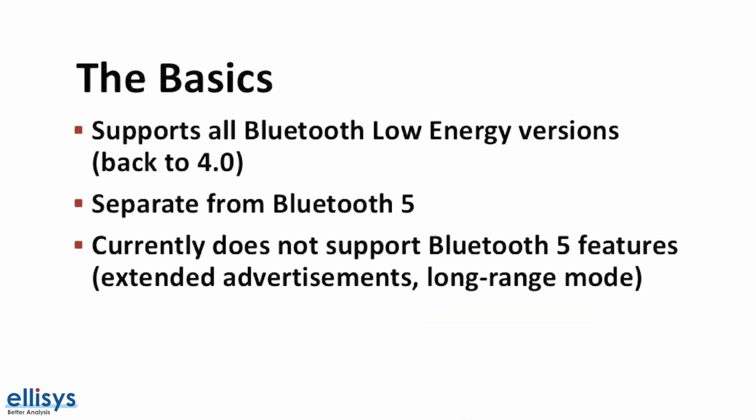A few important notes regarding Bluetooth Mesh. First, it supports all versions of Bluetooth Low Energy, going back to Bluetooth version 4.0. However, it is a separate specification and standard that's not part of the official Bluetooth specification. This is including Bluetooth 5 as well, and currently, as of the recording of this video, Bluetooth Mesh does not support the new Bluetooth 5 features such as extended advertisements and the long-range mode.